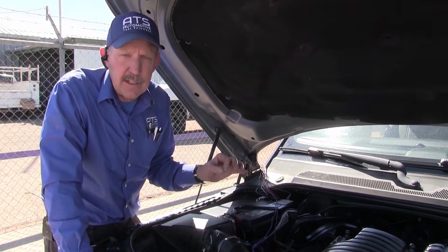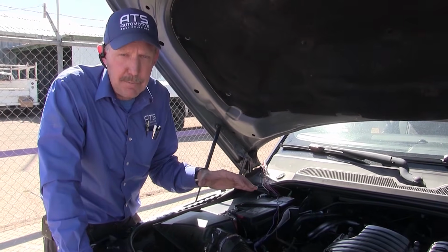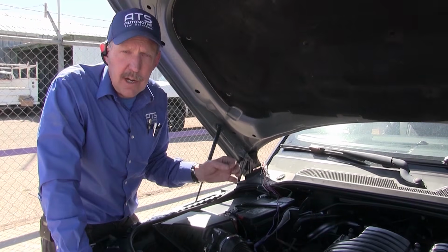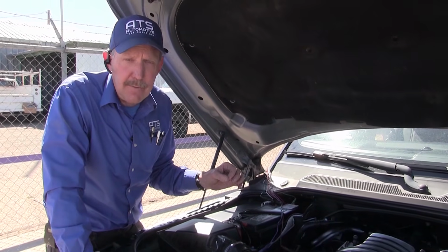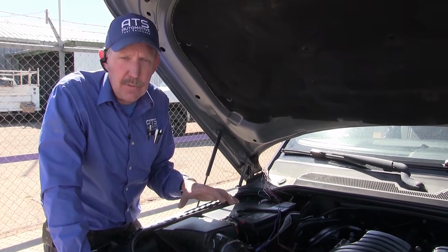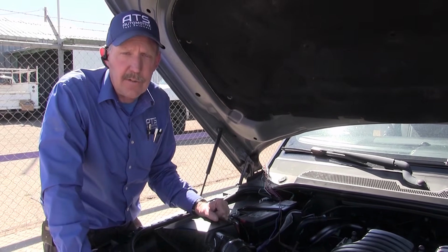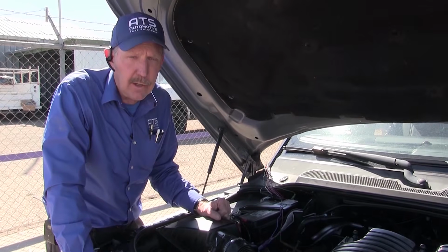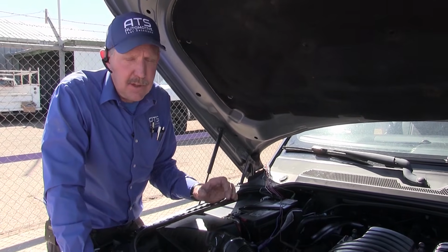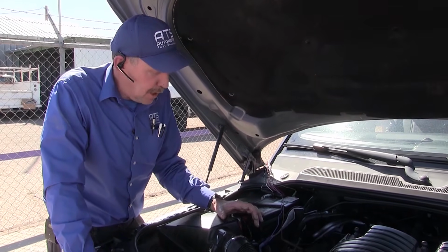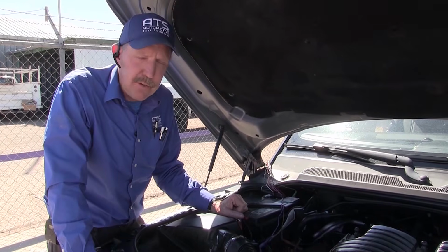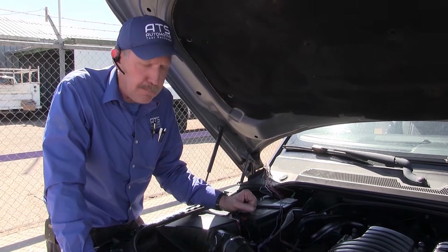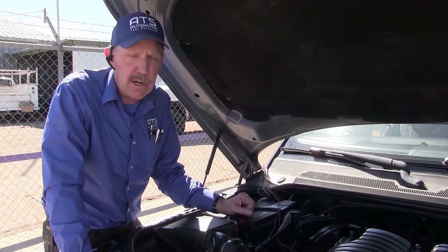Channel 3, green, is on the high pressure sensor for the high pressure fuel. Then I've got channel 4, blue, and channel 5, white. They're connected to the high pressure regulator. That is the control system that's controlling the regulated pressure. And then we've got purple, which is on the fuel injector for number 1, and brown is on the ignition trigger for number 1.